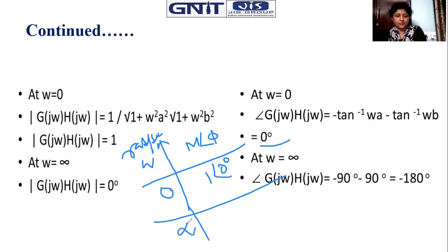And for the final value, omega you are considering infinite. So what is the magnitude? You are calculating, that will be 0 surely. And what is the phase? Minus 90. So what is your observation? When there was a single pole, it has ended up at the angle minus 90. But the system having two poles only, without any zero, ended up at minus 180 degrees. So pi, basically magnitude is 0 with the phase angle minus 180 degree, it will end. It is not degree, sorry, that was a mistake.